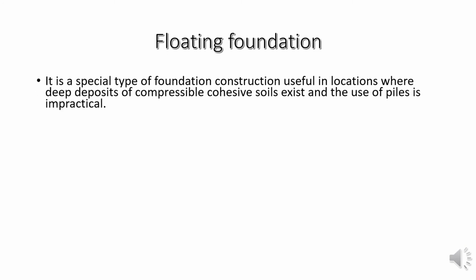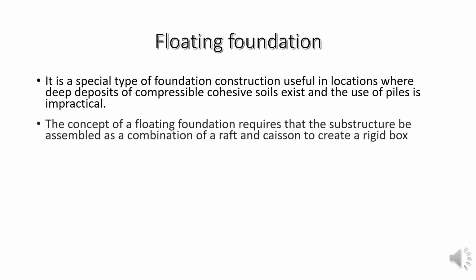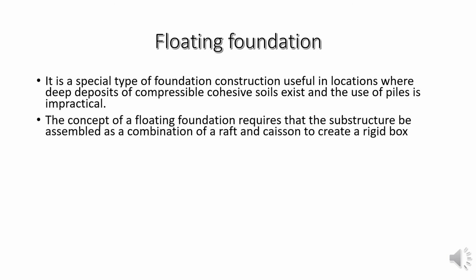Floating foundation. It is a special type of foundation construction useful in locations where deep deposits of compressible cohesive soil exist and the use of pile is impractical. The concept of floating foundation requires that the substructure be assembled as a combination of raft and caisson to create a rigid box.